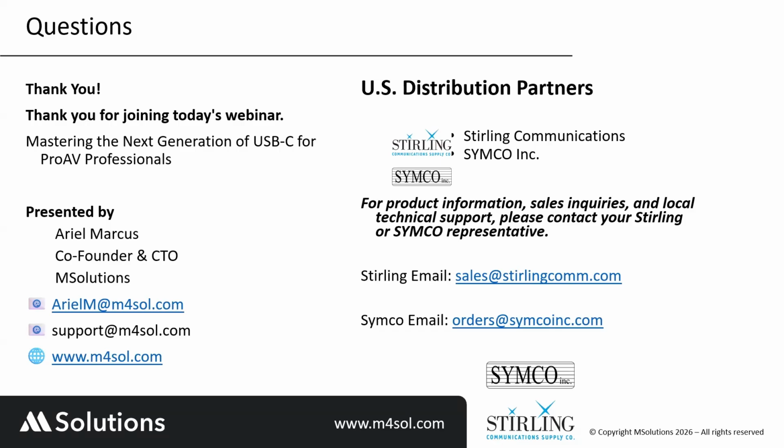There are 4 pairs of high-speed lanes, and it doesn't matter what the frequency or the bandwidth that they will support. If it is rated USB 4, for example, it's defined that it can support 2 lanes of DP video and 2 lanes for data. So yes, USB 4 and Thunderbolt will support the video and the data at the same time. And USB 2 is being supported by default.